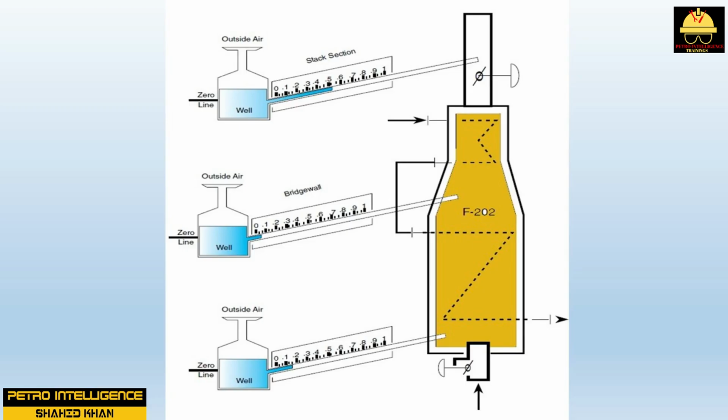Stack damper. Combustion gases leave the furnace through the stack and are dispersed into the atmosphere at a height to ensure against any immediate deleterious effect such as carbon monoxide poisoning. As the hot air rises in the stack, it entrains combustion byproducts and carries them out of the stack. This natural draft creates a lower pressure inside the furnace that is essential to good operation.